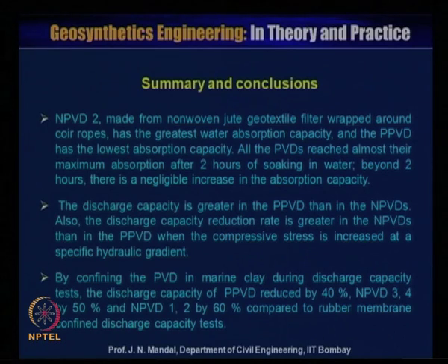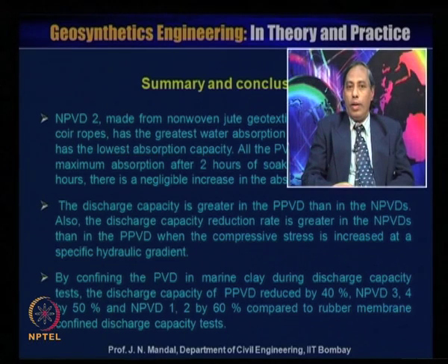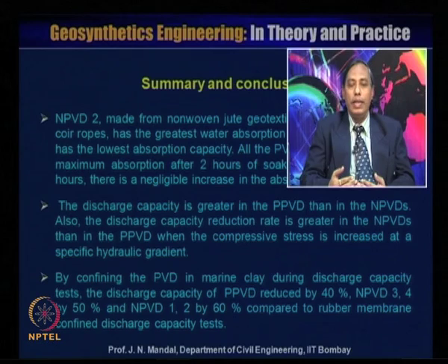Beyond 2 hours, there is a negligible increase in the absorption capacity. The discharge capacity is greater in the polyester prefabricated vertical drain than in the natural prefabricated drain. Also, the discharge capacity reduction rate is greater in the natural prefabricated vertical drain than in the polyester prefabricated drain, when the compressive stress is increased at a specific hydraulic gradient. So, you should maintain that hydraulic gradient.